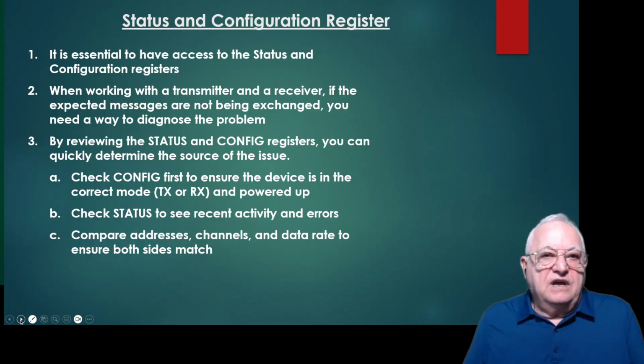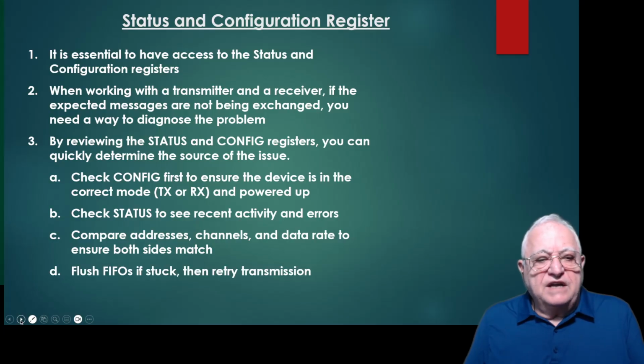So you do that in both sides and make sure they both match. Then you flush the FIFO. If stuck, then retry the transmission. So basically, you see the status and configuration and say, okay, it seems it got configured as I had expected, or maybe something went wrong.